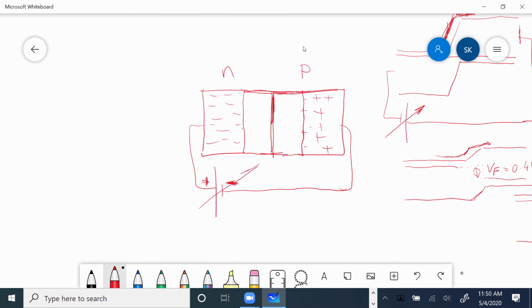This is that much voltage. How about applying, for example, say V equal 1 volt. I'm just making up 1 volt. And then I'd like to apply a high voltage. Say I apply 10 volts. And see what happens to that. I can see that the depletion region gets even wider. That's all of that is depletion region.